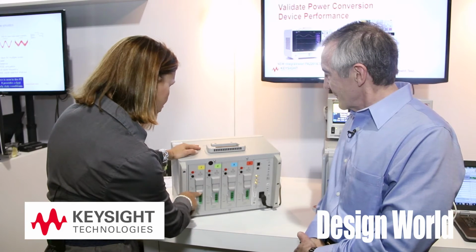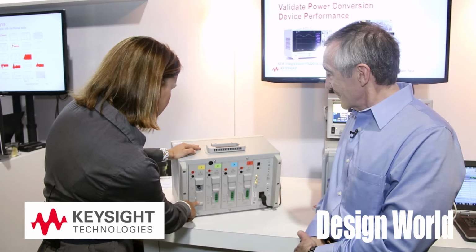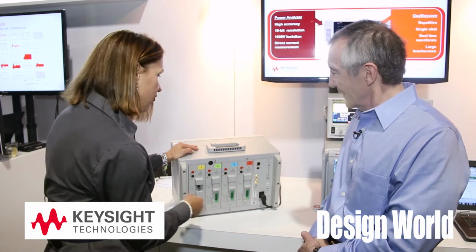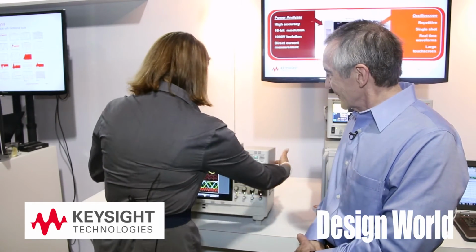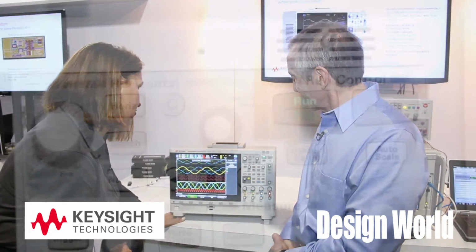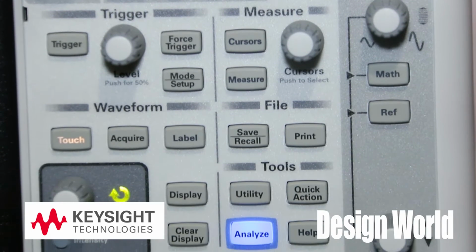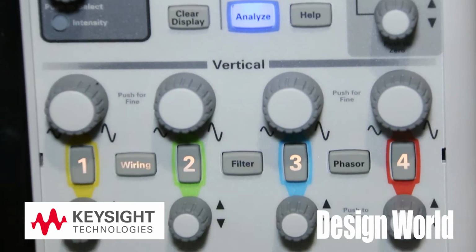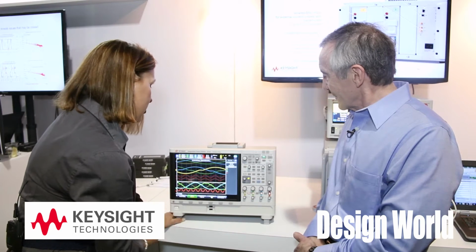And if you want to measure a higher current or you don't want to break the circuit, then you slide this door down and you can measure it through BNC connector via probes or CTs. I'm running some simulated data here just to be able to show you what this does. This is the scope view where you can assess and evaluate everything just like on a scope. You can change your time base and scales, zoom in and out.